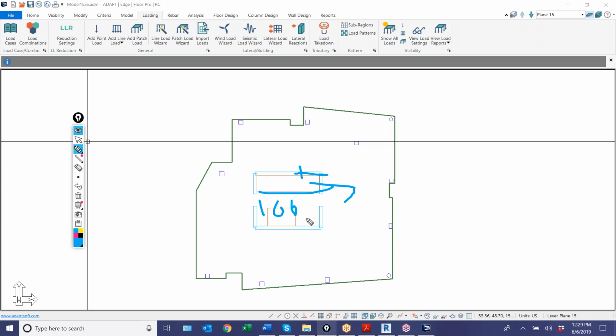We basically take this total force, which I'll call F, and for every node that's generated and connected to this level, we take the mass of a single node divided by the sum of the mass connected, times the force, and we apply that force to each node. So every node gets a portion of this total force. If there's eccentricity and you also have moment, every node gets a portion of this moment as well.